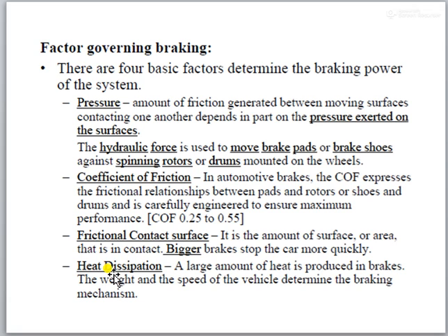Okay, after that, heat dissipation. A large amount of heat is produced when the braking action takes place. So to absorb that heat dissipated by the braking action, we have to do something, so that the braking efficiency is not affected. Whenever heat is released during braking action, that is responsible for reducing the coefficient of friction, it helps to damage the mechanical parts, and it pulls down the efficiency of the braking action.